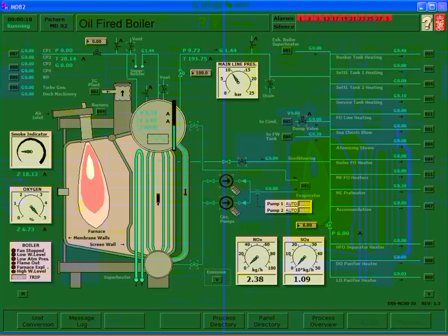All that's happening is that energy from the superheated steam is being transferred back into the water in the drum until it reaches equilibrium. So you really haven't lost anything by superheating that steam up, because now that you're going back to saturated, you're just transferring the heat back into the drum.